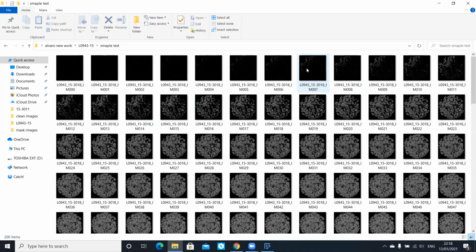It's very important to put the scale in imaging to give a right measurement, because we measure a lot of air void measurements. For example, the air void diameter will be in millimeters. So the images need to have the scale. You need to have X, Y, and Z from the operator to start working. That's the first thing you need to do.